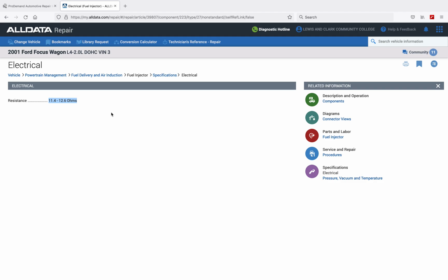And something you want to consider, these are not always going to be 100% accurate. These are numbers that are derived by the aftermarket companies subscribing or having access to the OE side and rendering it in an aftermarket format like ALLDATA. Having said that, if the OE says this is an acceptable range, the aftermarket is going to use the same approach for finding what the acceptable range of resistance is going to be within a circuit.